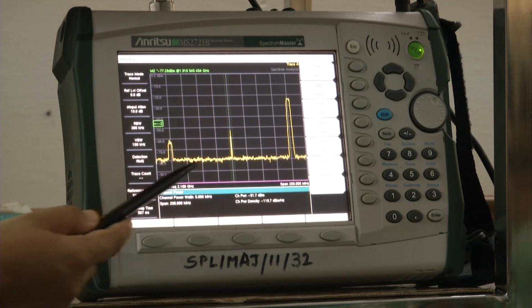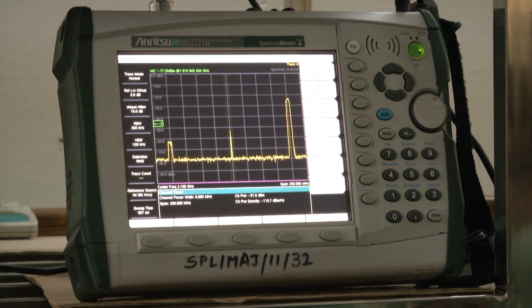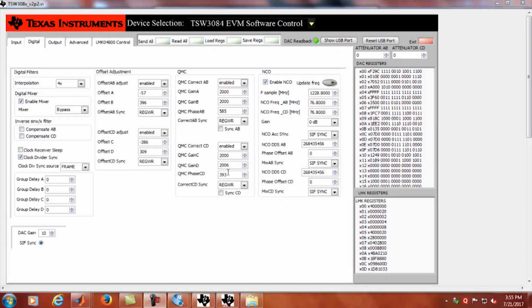So this is the IQ imbalance effect which we are facing from the actual transmitter there. So how can we reduce this? As I told you, we can use two coefficients just to tune it. So in this case, instead of using least square and digital predistortion, in two steps, first we adjust the IQ imbalance by tuning these K1 and K2 values.